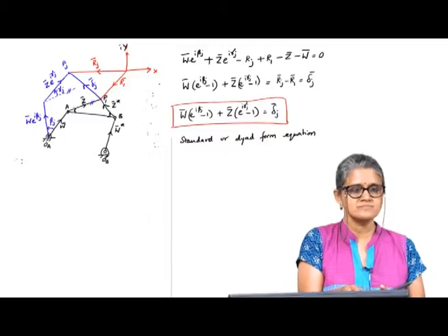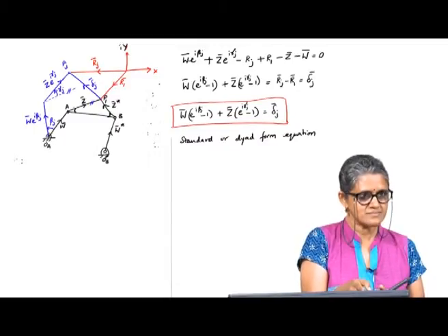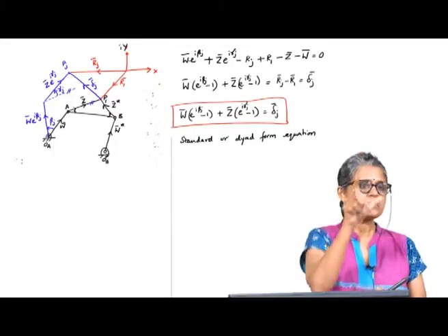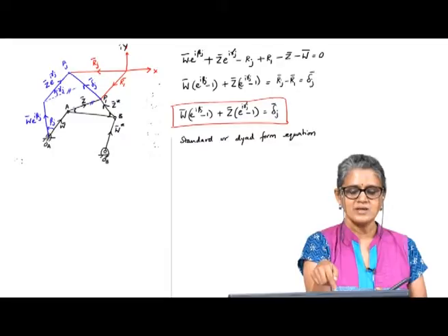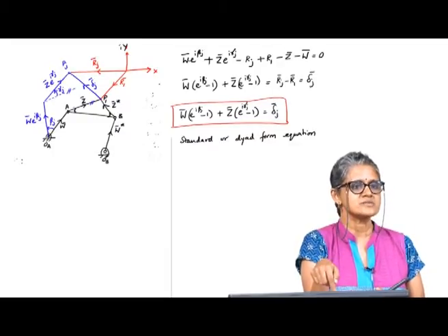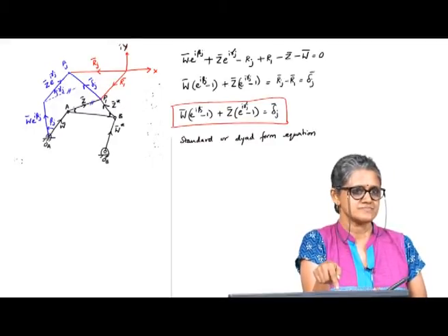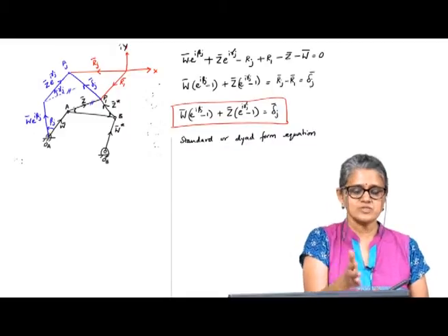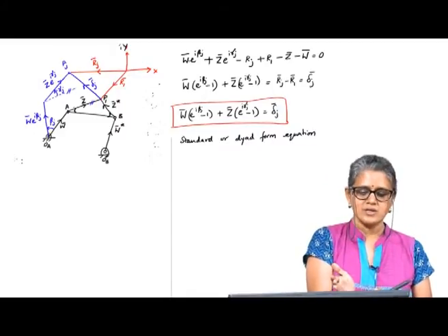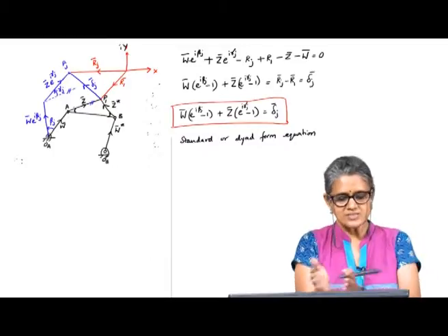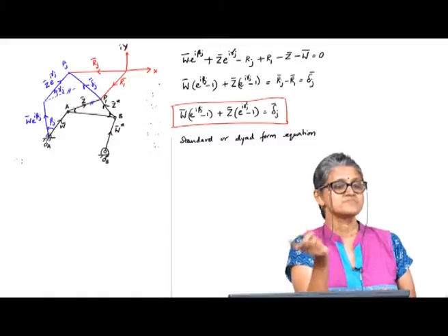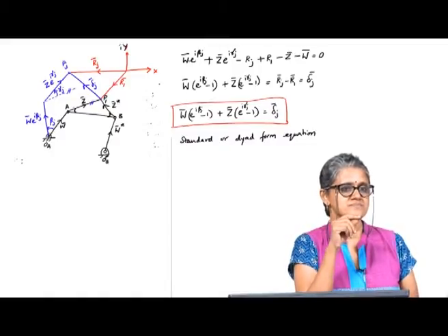So, knowing beta j and gamma j, for instance, you will want to find out what should be W and Z to hit these points defined by R1 and Rj. Okay, then we will also look at function generation, for W and Z with certain angles, W star, Z star, what the angle should be, so that you can do the synthesis of your linkage.